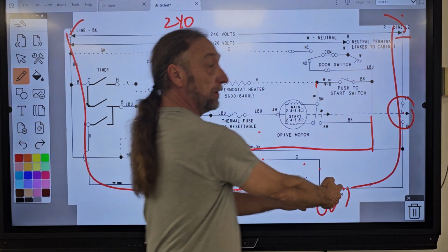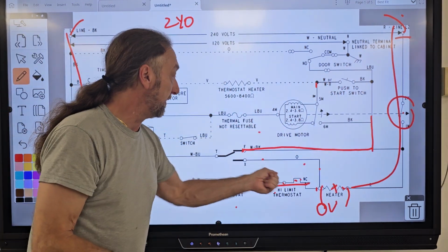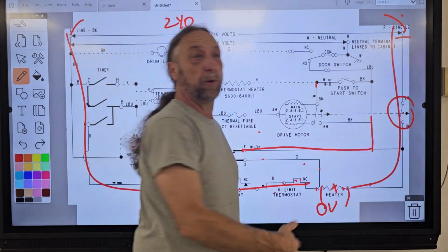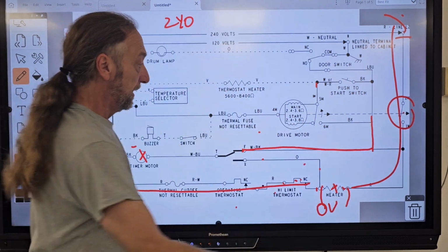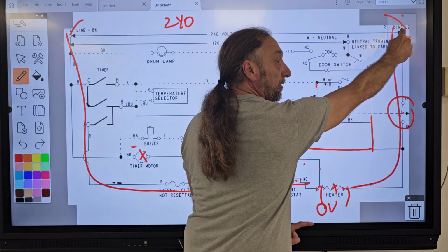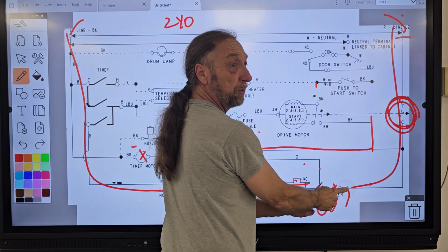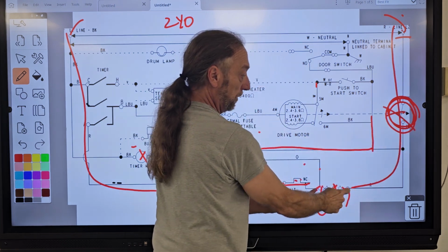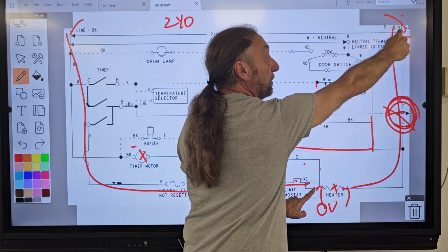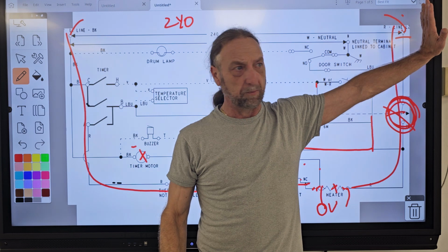Now let me show you on the wiring diagram what I'm talking about. So I'd have my 2 meter leads here. I need to know which way my problem is, but instead of starting to test like this, I can't get to that motor without taking the machine apart. But if I take this meter lead off and go from here to here, and that is my problem, what will it say here if this is what's broken? 0. But what if I put it here? It'll be 240. Then I know my problem is here. Does it make sense? Yeah.